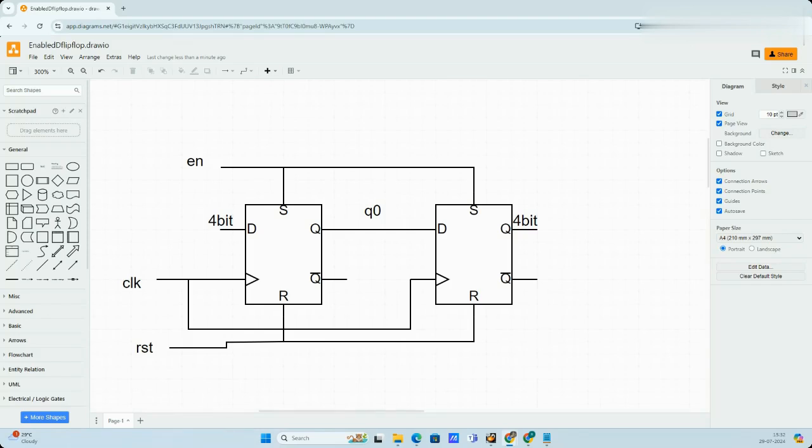So basically, the issue that we are facing is that if we are not using a synchronizer, it produces an output Q within an unbounded amount of time, so the output Q will depend on D. Whenever there is a falling edge, if D is 1, then output Q may not be 1 because it will be 1 only at the rising edge. But during this amount of time, if D doesn't remain 1, then output Q will not be 1 within that time.